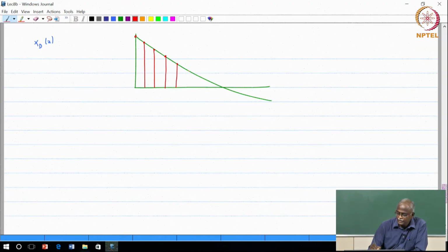Okay, these are the samples that are obtained. Again, this is the sampling process, and this is something that we well understand. This is uniform sampling at a given sampling rate. Now, if I have downsampled this signal by a factor of 3, that means this sample remains, this remains, this remains, this remains, and this remains. The other samples are not there. So, in other words, my samples now are this, this, this, this, and this.